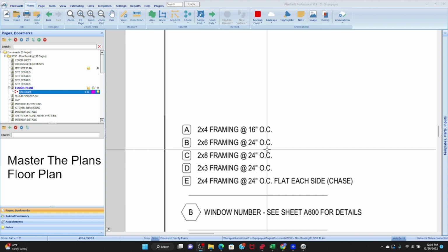And so if you want to think of it in most general terms, we'll put one stud in the very center of the wall, and then we'll place other studs 16 inches on either side, every 16 inches. And so when we have to do the material quantities, which we will, because we go from the cost estimate to the material quantities, we'll be able to tell how many studs we need for any length of wall, because we can do that math.